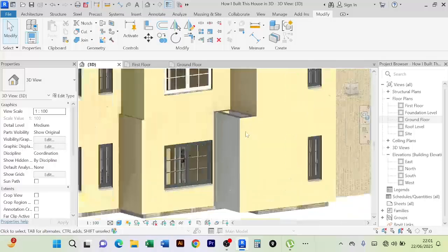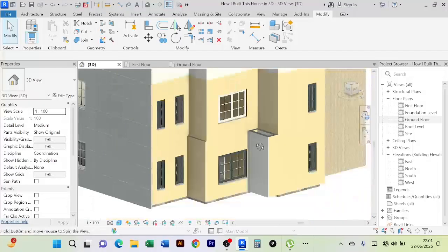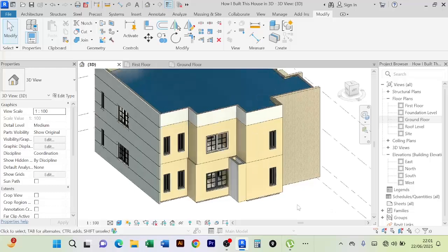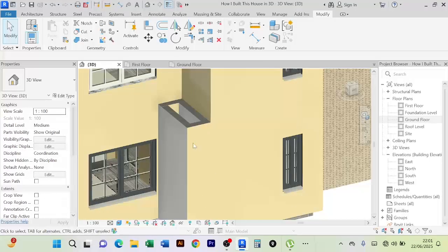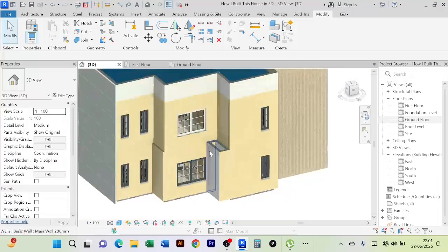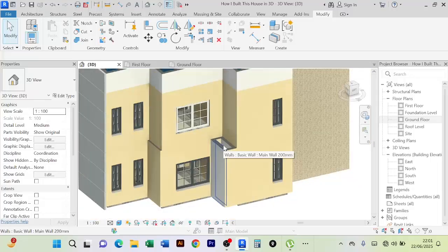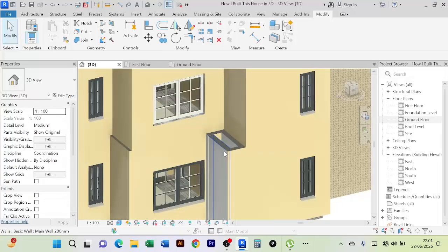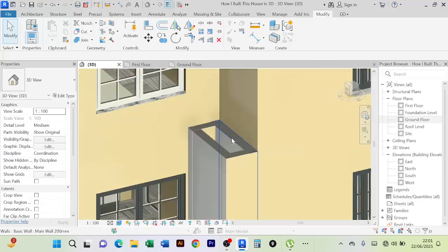When we come to the 3D, you should be able to see this wall here. See that? This will act as our duct. A duct is really an opening that collects rainwater from the slope of the roof, and it channels this water to the manhole. This water is supposed to come from the gutters to the duct, from the duct to the manhole. So just like that.